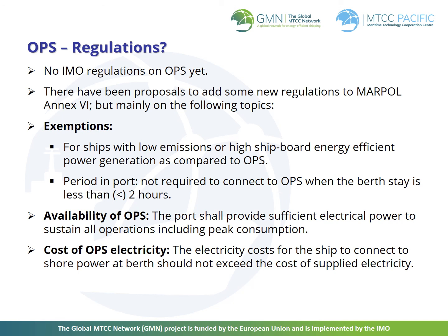Currently, and at the time of writing this document, there is no IMO regulation on OPS. In fact, IMO has developed minimal regulations on port development and operation other than those that may directly be required for ships' operation, such as reception facilities. Thus, there have been proposals to add some new regulations to MARPOL Annex VI on introducing some ship requirements for the future wider use of OPS.